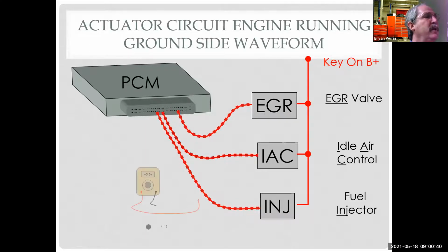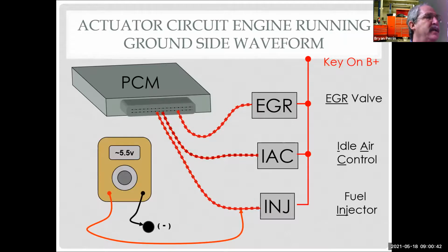With the engine running, I can see that, hey, something happened. Is it the right amount? I don't know, but I no longer have system voltage, so I know the computer's turning it on and off. So whether this reads 9 volts or 3 volts is really immaterial unless I have a scan to compare duty cycle to. Here it's an injector, so it's pulse width modulated. I'm just looking, does the voltage move at all? Is something happening here? Because this is the only tool I have.